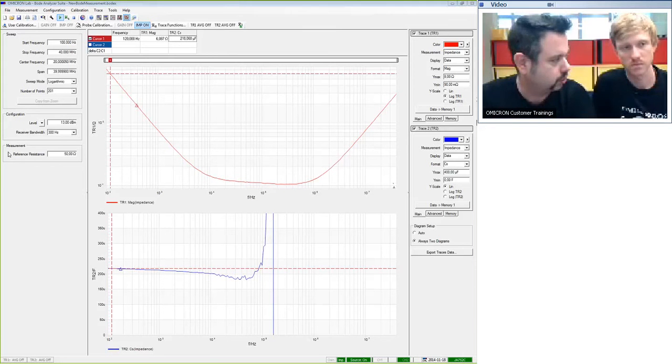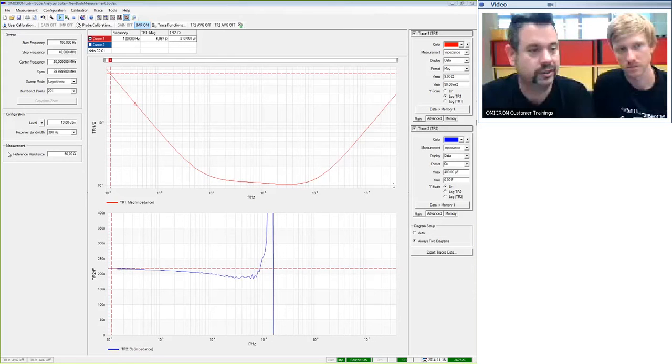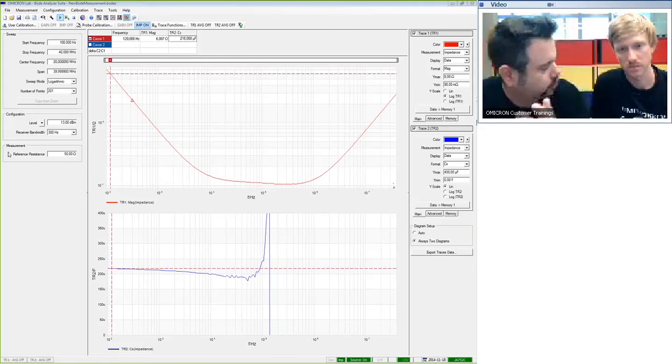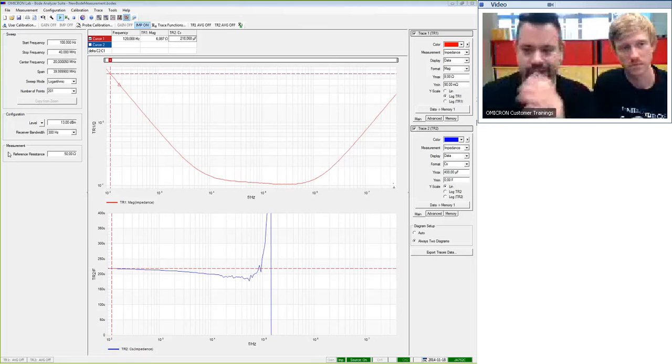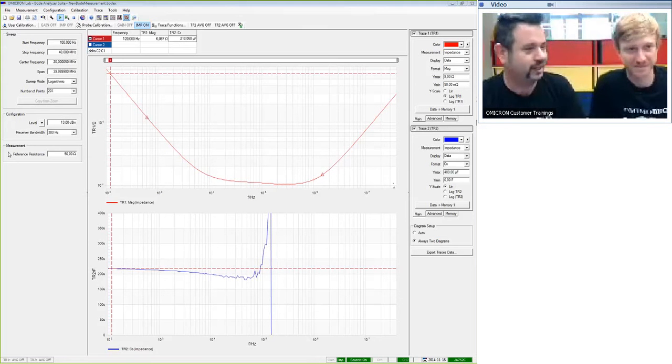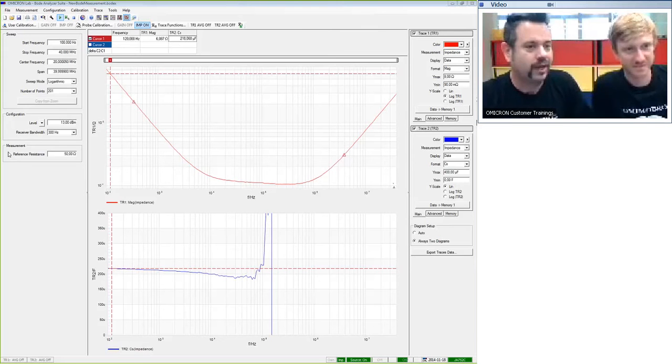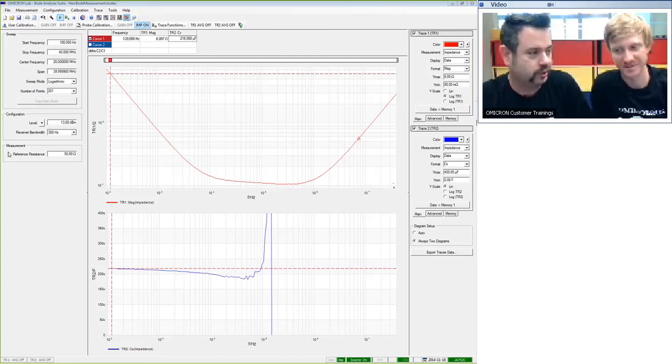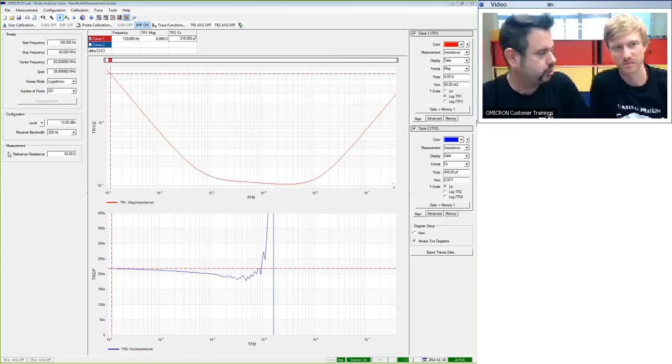and you make an open. So this is quite important, because if you have, for example, what's the name now? Keysight? Yeah, I always say HP because I'm an old guy. So if you have a network analyzer of one of these companies with many names, and you perform a load calibration, and you don't connect the load, it will still calibrate, and then you have the mistake as well. So that's a common problem in general with vector network analyzers. Therefore, always after you've done the calibration, use something you know, put it in, and check if you get a correct reading. Then you know that your calibration has performed correctly.